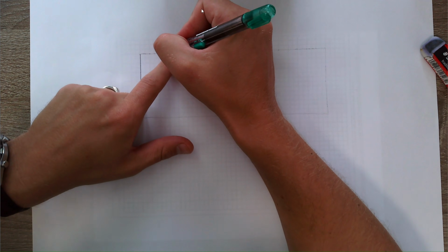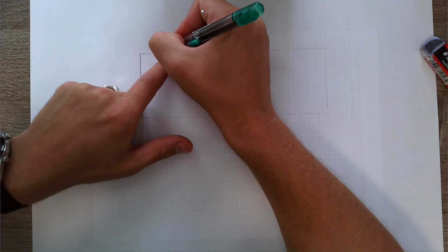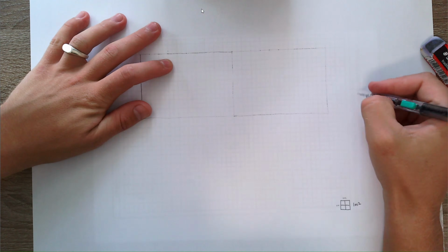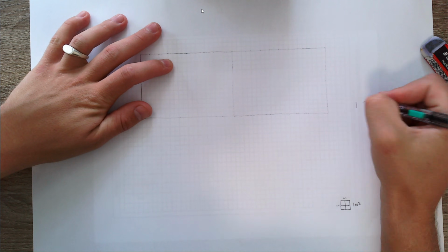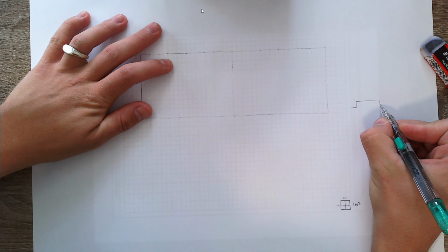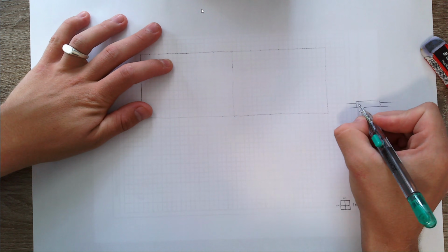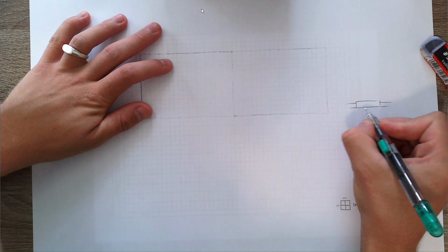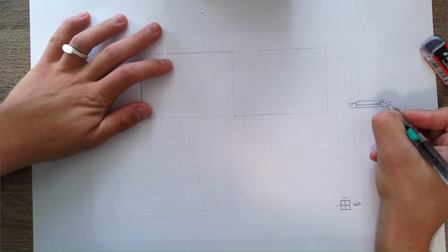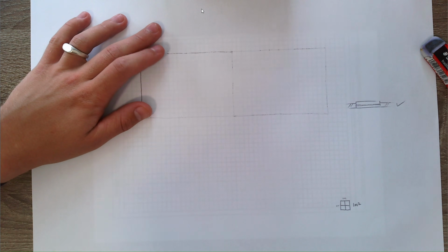I'm going to make the thickness of the walls a half of a block. And when you give a window, remember that you need to show the window sill. So if you put the window into a wall, we show the wall thickness and then we also give the window sill and we add in the window frame, and don't forget about the hatching. This is the correct way to show your windows on your floor plan.